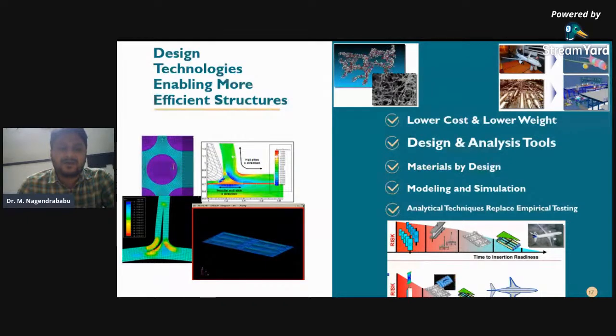CMCs are comprised of a ceramic matrix reinforced by a refractory fiber such as silicon carbide fiber. They also offer low density and weight and high hardness, and most importantly, superior thermal and chemical resistance. Like CFRPs, they can be molded to certain shapes without any extra machining, making them ideal for internal aerospace engine components, exhaust systems, and other hot zone structures, even replacing the latest in HRSA metals listed earlier.